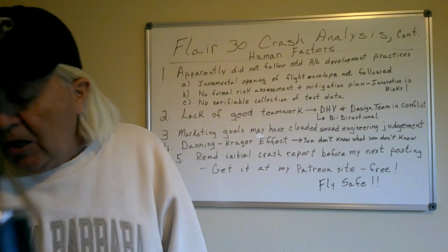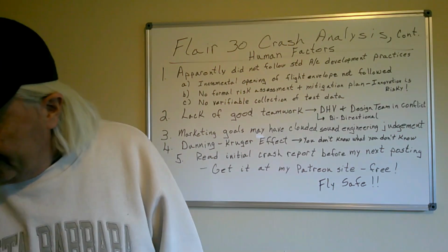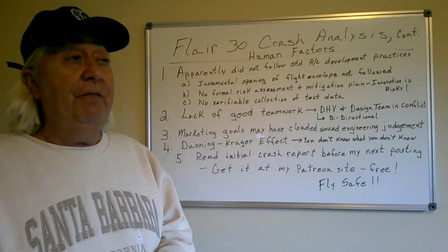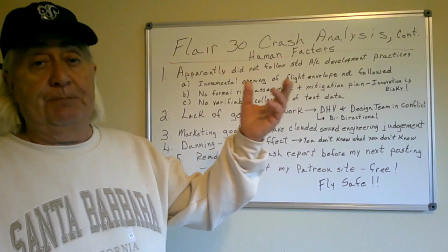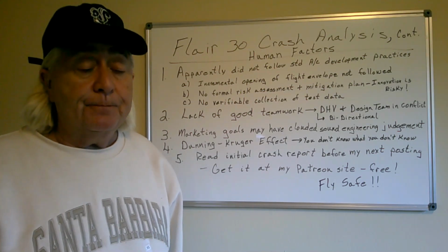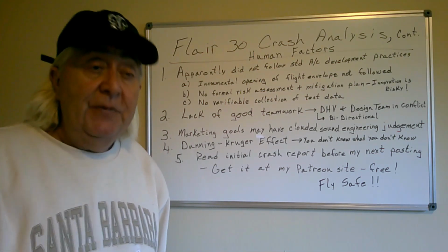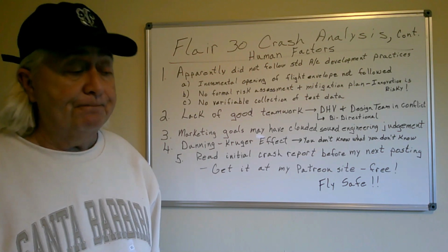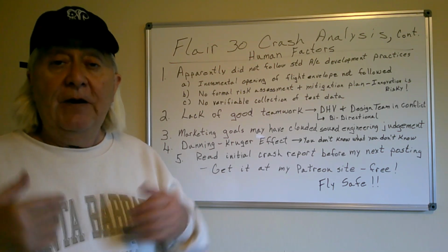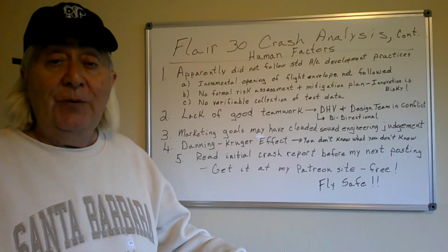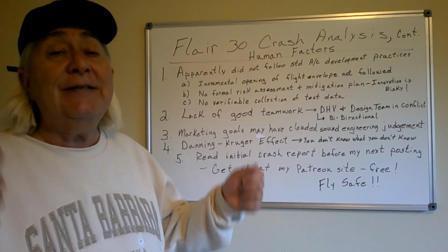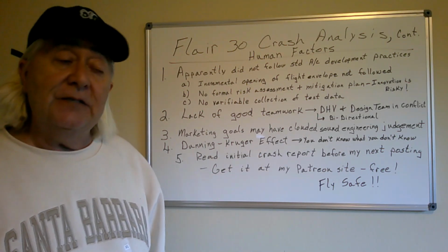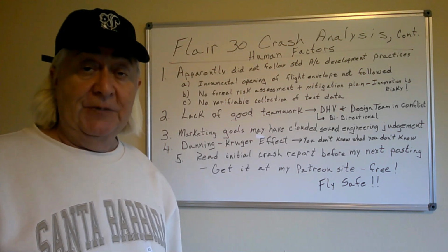Hold on one second here. And those photos with the tufts on there might exist. If they do and you have them, post them. But at a minimum, you're going to tuft your wing even before your first hop. Myself, I put tufts on my wing. I go stand in the wind. I don't even leave the ground. I don't even attempt to fly. And we look at what the tufts are doing. And we acknowledge, okay, it's not the right Reynolds number range, but it tells me something.